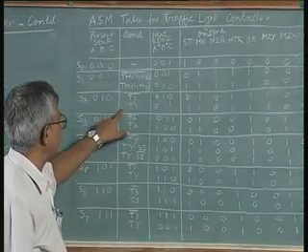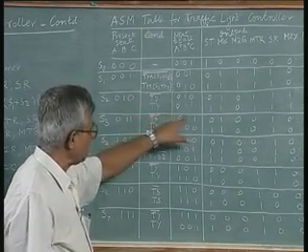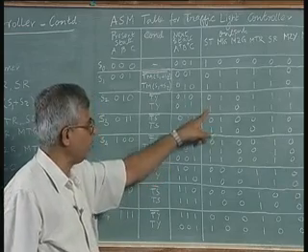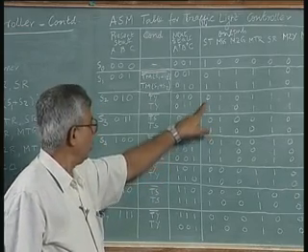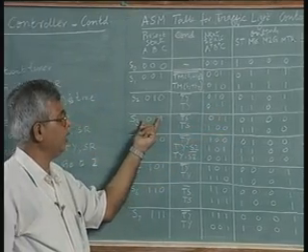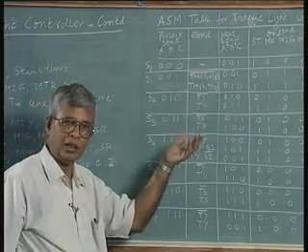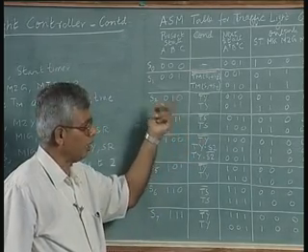When the time is over, everything is same except that we start the timer. So the same set of outputs with start timer 1, and then it goes to next state 0 1 1, wherein now the yellow has completely turned, it has become now red, and the turn has become green.